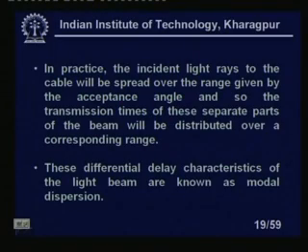So, the light is taking more time; it is not equal time that it takes to reach the end. But this problem can be eliminated in the case of graded index fibers. Because the problem we talk about is in multimode step index fibers, this will be more; you will find it easy to see this in graded index fibers. These modal dispersions will be almost eliminated in the case of graded index fiber.